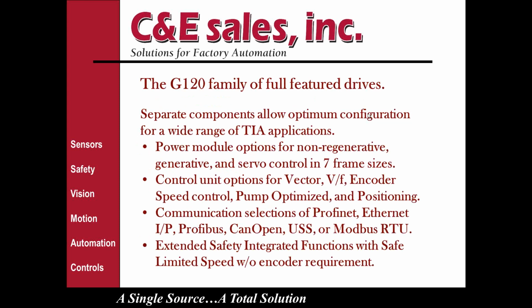Most of the G120 family, with one exception, we'll talk about the G120Cs in a couple moments, are made up of separate components so that you can have an optimal configuration based on your needs. One of the components that's required for every drive is a power module, and there are several different flavors of those available, from a non-regenerative, basic power module, through a fully regenerative power module that can regen voltage back out onto the line in a nice, clean fashion.